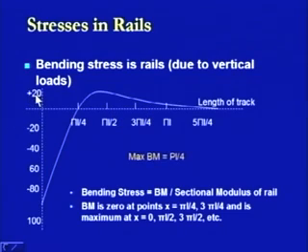That is how the effect of the bending stress will be seen, and we have seen this effect of bending stress in terms of the single wheel condition and the multi wheel condition in the previous lecture also. That is how the relief of stress may get induced because of the overlapping of the bending stress diagrams induced due to the different wheel conditions.